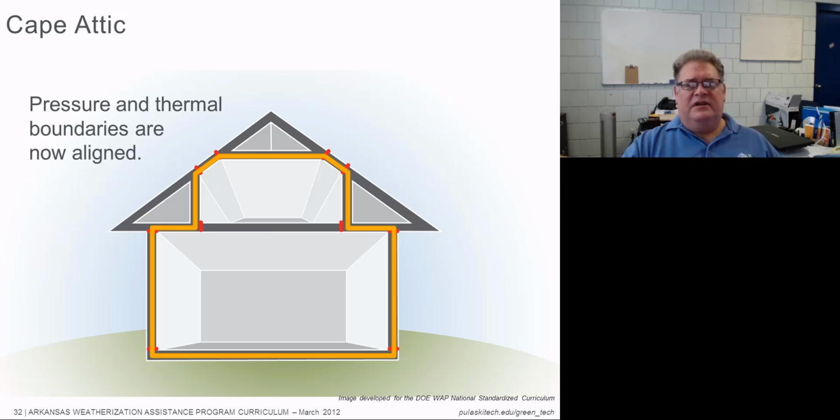We also want to air seal the intersection where the sheetrock or other air barriers transition on that slant wall at the top and bottom. We don't want air moving up this wall and into this attic. We don't want it moving from under here or here up through the wall. Now, to move this way and back out is fine, because that's going to help keep the roof decking moisture free, or at least that's what the codes tell us. So if we're going to buy that, then that's what we need to do.